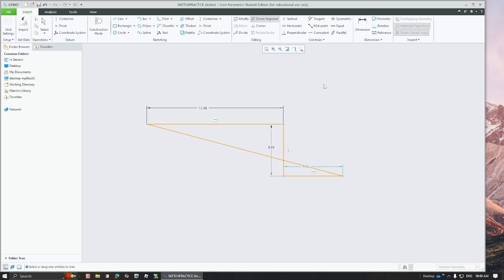So you can just drag these lines and make it pass through whichever entities you want to delete. And as soon as you have a closed single entity, it will get shaded like this to show that it is ready for extrusion or any other 3D modeling features.